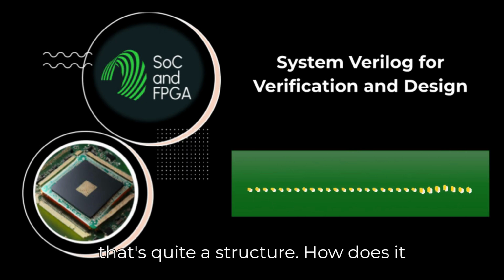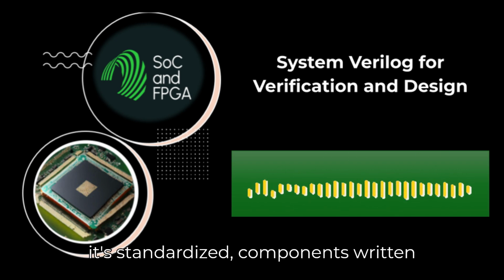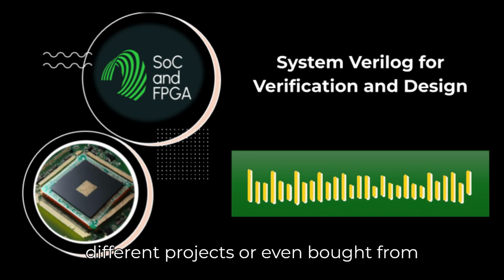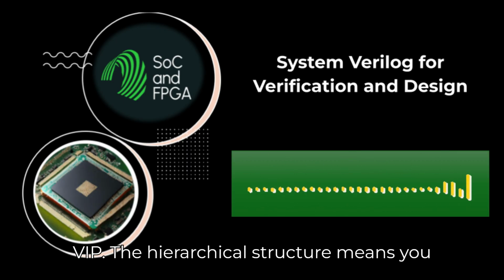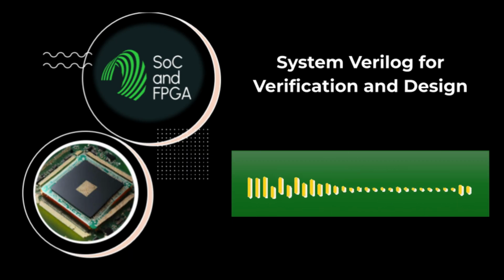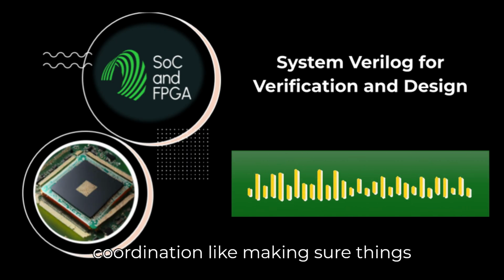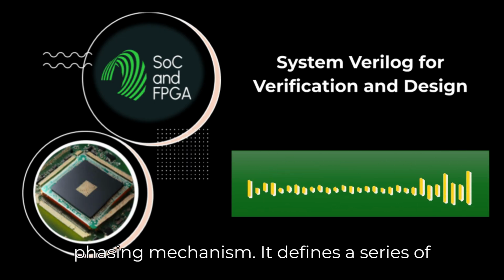Wow, okay. That's quite a structure. How does it promote reusability? Massively. Because it's standardized, components written using UVM, like an agent for an AXI bus, can potentially be reused across different projects, or even bought from third-party vendors, verification IP or VIP. The hierarchical structure means you can build a testbench for a small block, then easily integrate that block's verification environment into a larger system-level testbench. How does it manage coordination, like making sure things happen in the right order? That's the UVM phasing mechanism.